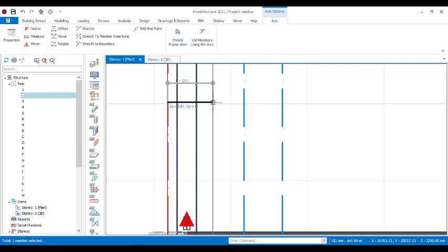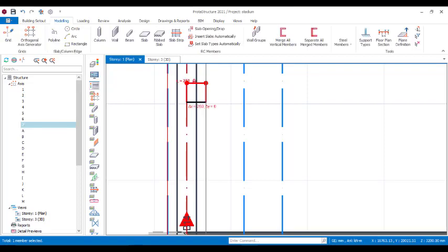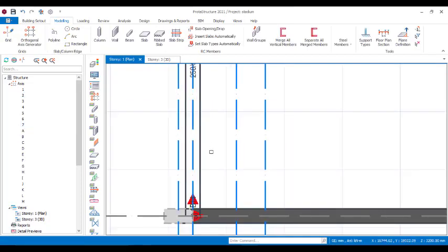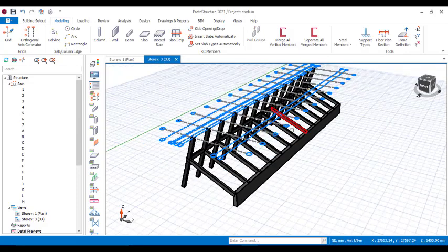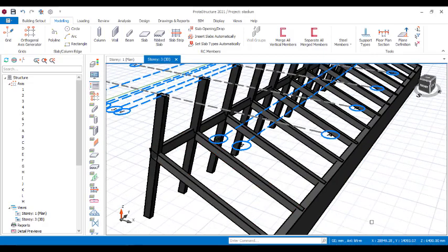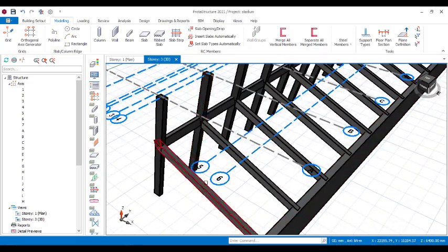Okay, so F2, and then that's 250, right? 250, then enter. Okay, so exit. So now we have the axis at the center of that beam. In case we want to do anything with the beam, that will be easier for us. Okay, so now we will draw the floor.